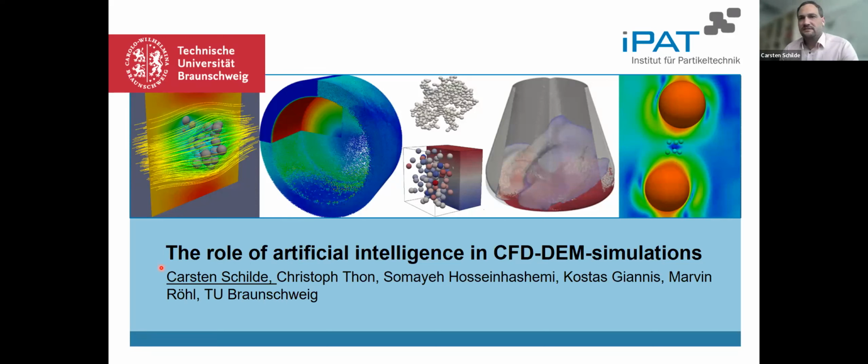But the main question is how much energy will be dissipated within the deformation of grinding media, since we have product particles in between, which often have a lower Young's modulus, for example, or they have a certain strength. And so there's a lot of energy dissipated into the particles. So it's difficult to handle this. But in principle, that's it.